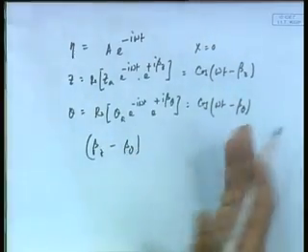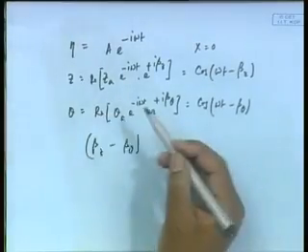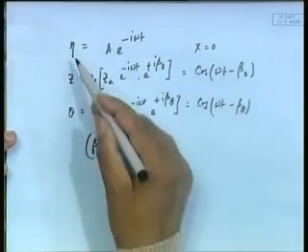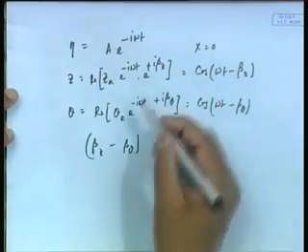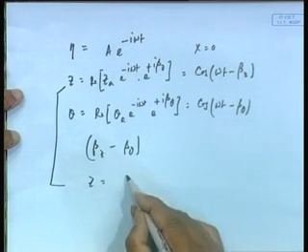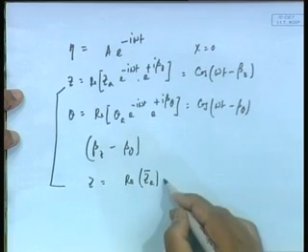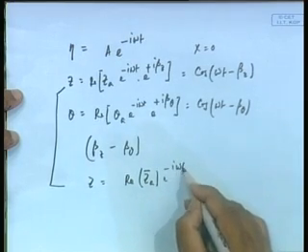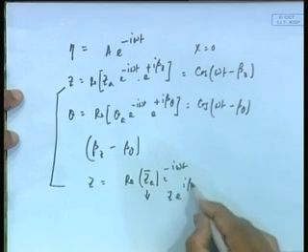This is my phase gap between z and theta. Normally what I will do, as you will find in later solutions, is write this as the real part of z a bar e to the power of minus i omega t, where z a bar is equal to za e to the power of i beta z.